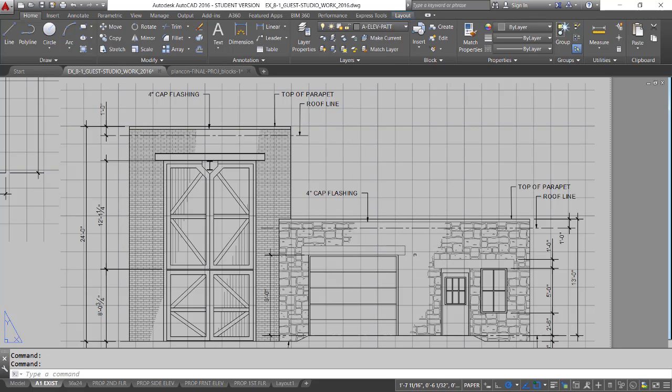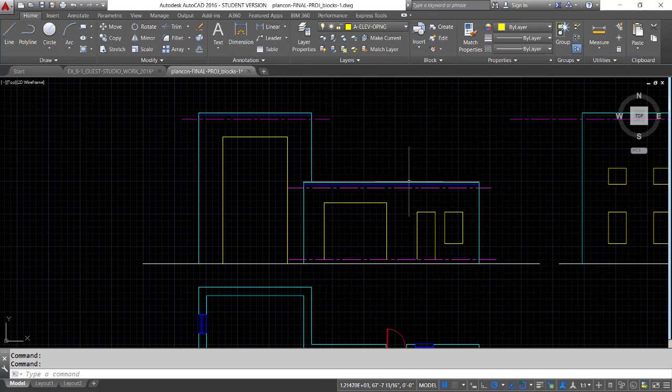We don't want to fill the entire thing too much, because we do want some space available so that our text and our dimensions are not covered over. So for instance, this one that shows the height of the overhead door is sitting on top of this brick hatch pattern, and you could consider that being obstructed, not quite as clear as to what that is. So it might be something we'd want to avoid. And containing our pattern to certain areas is one way of doing that. So let's go back to our drawing here.